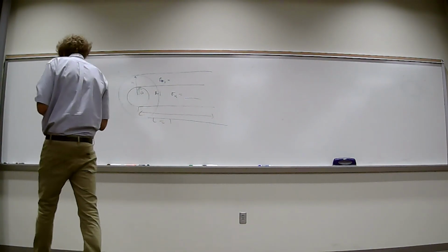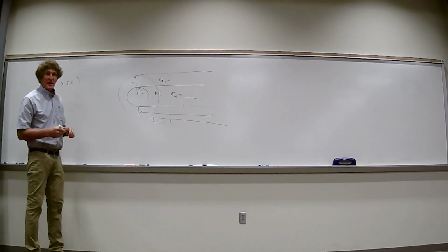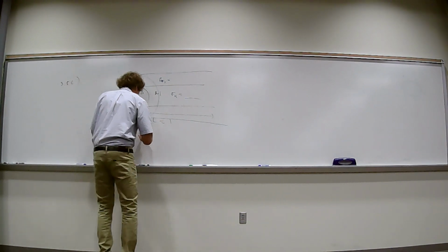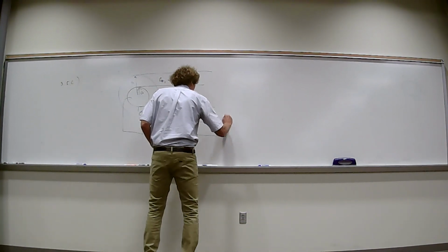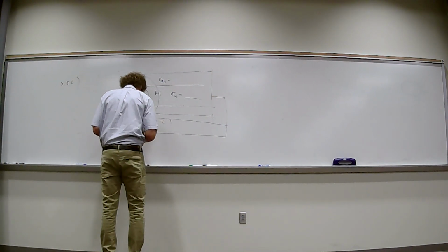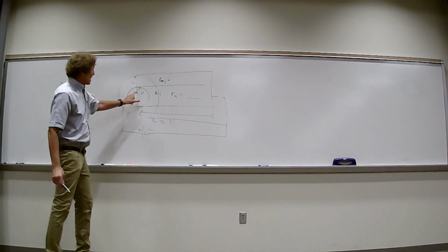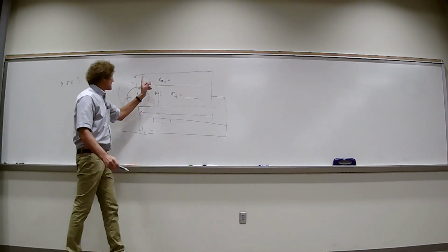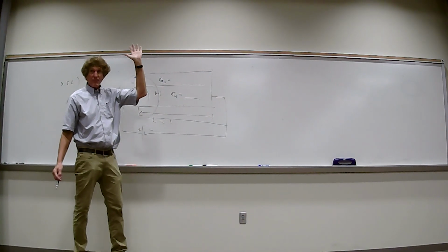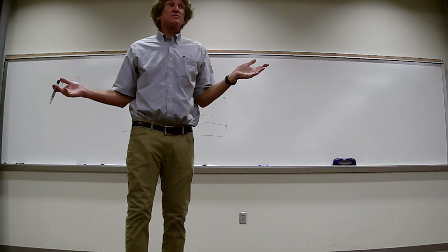Now, take a look at this. Can you see what this problem looks like? Because remember, when you're talking about resistance, when we put a plus-minus voltage across there, the same voltage is going to be across the inner core as the outer sheath. Do y'all follow me on this? Same voltage, so they're in parallel. Same voltage across any two resistors, they have to be in parallel.